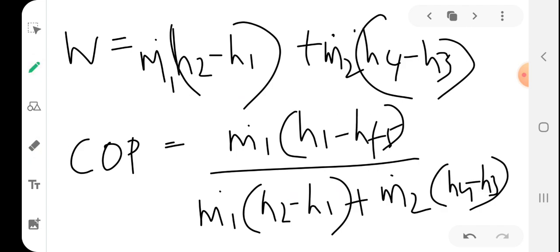Okay, now a very important, crucial problem we are encountering here is with m2 dot. We may not have an idea of m2 dot, but in questions, the mass usually given will be the mass that is flowing through the evaporator.